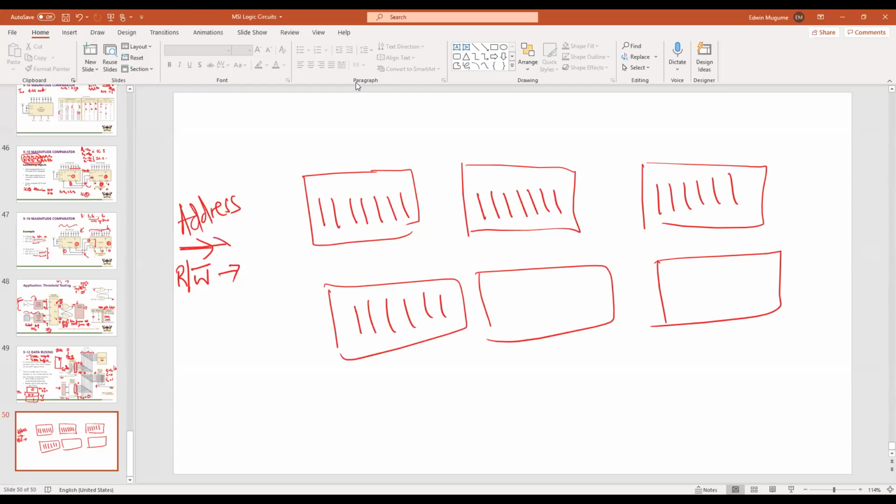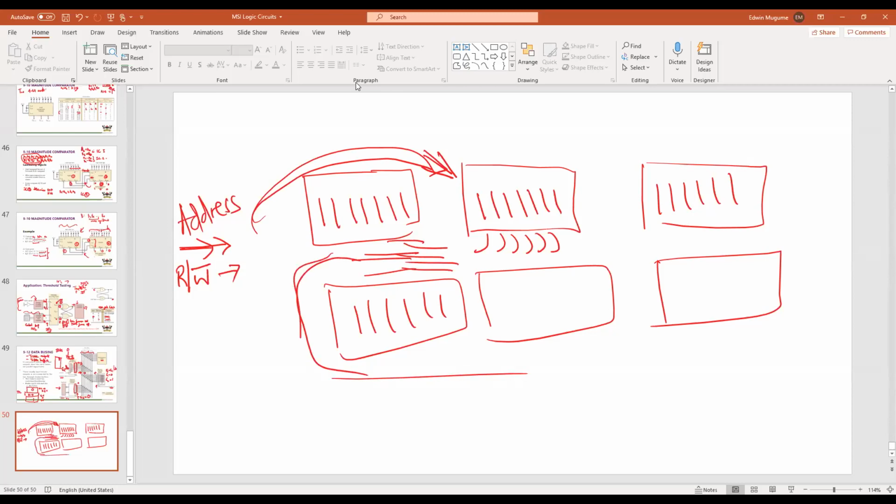Now this address will be unique to one of these. Let's say that you have picked this address. These 8 bits can go on the bus. Okay, so you have buses running here and they will connect through here and so on. And so if you have selected this address, it will enable the buffers here, but it will disable the buffers on all the other registers, all of them. Okay, so that address is the one that enables the buffers, particularly of that unique register that you have transmitted.